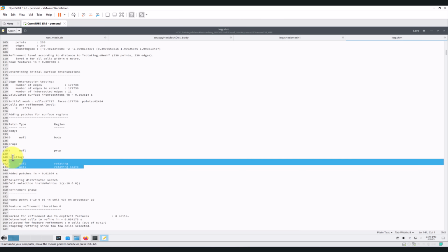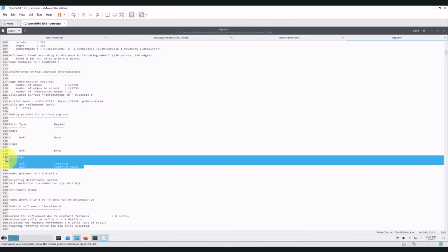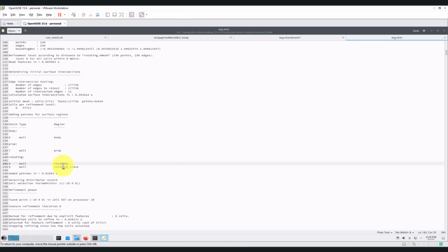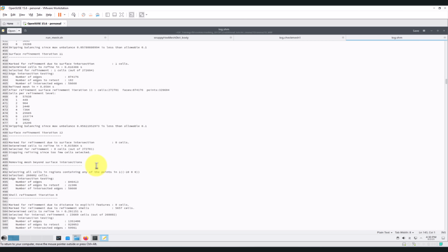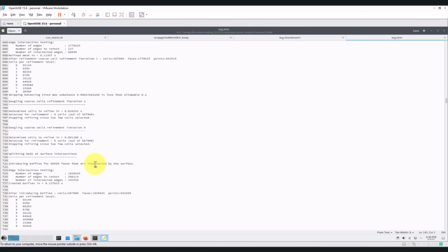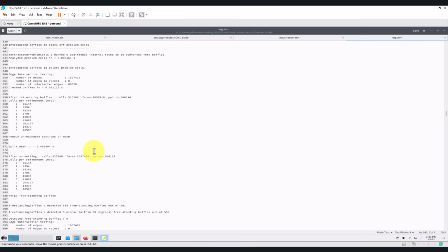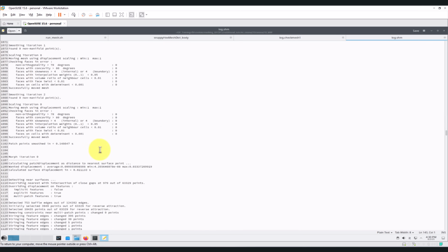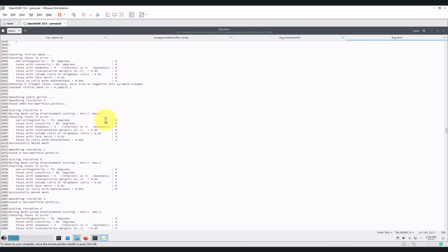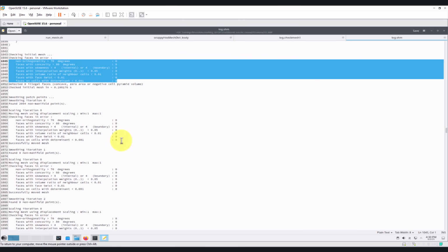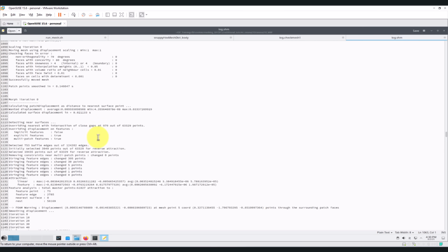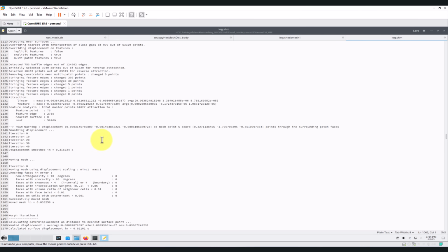Look at that now: if you check the previous case, this didn't exist because we were not creating that. So this name is created automatically. Then it will be renamed. Okay, and that's it. So look at that. You start the whole process, the cell splitting and so on, the castellation, and it starts to measure the quality. As you can see here, pretty much 0 cells are violating your mesh quality requirements. Usually that is the case for Cartesian meshes. They're all Cartesian, so everything should be perfect.